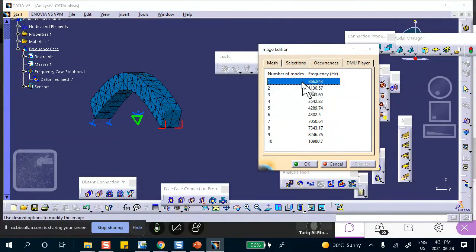You're absolutely right. Below or above. If it's below, no problem. But if it's above, you're going to cross this. And the idea is that if you ever cross a resonant frequency, make sure you program your device so that it doesn't sit there for a long time. Go through it very fast, one way or other. Or try to completely avoid it. Okay? Does that make sense?